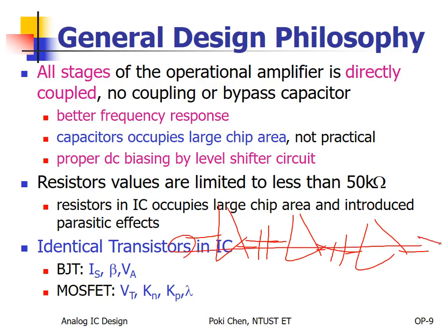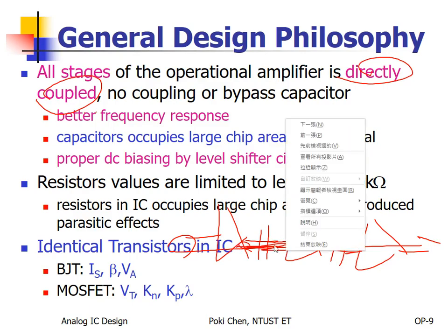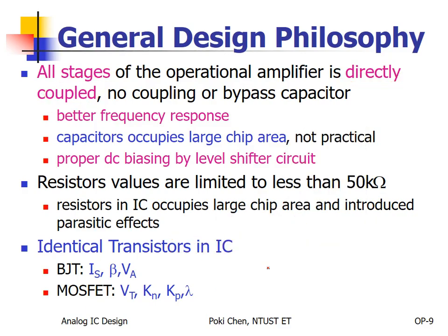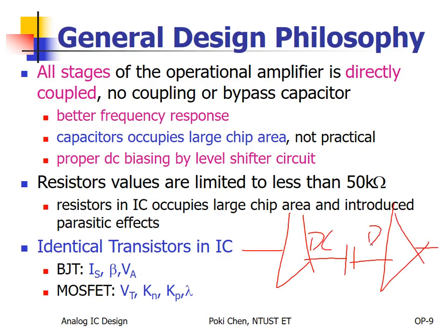It will be blocked, right? So you need to apply direct coupling. It means my output directly to your input. But what is the problem? Why do we need such kind of AC coupling in microelectronics? Usually it means my output DC bias doesn't fit your DC input bias.